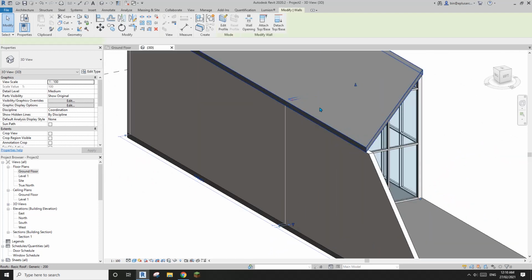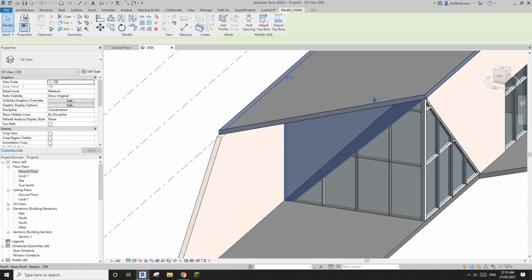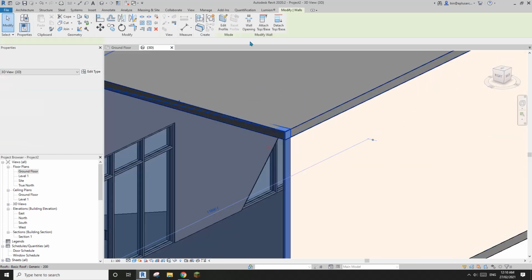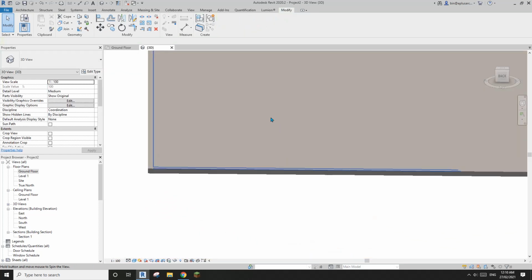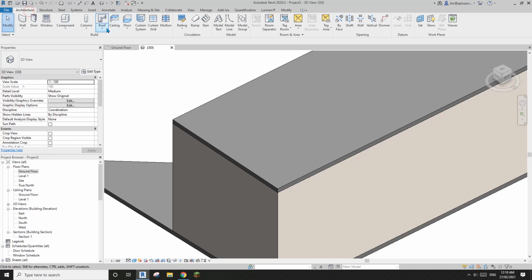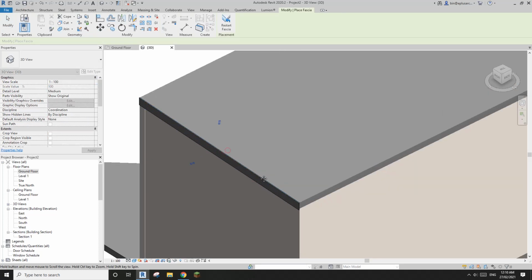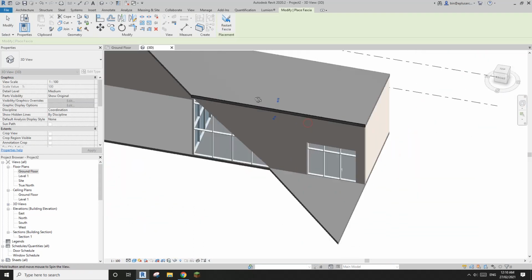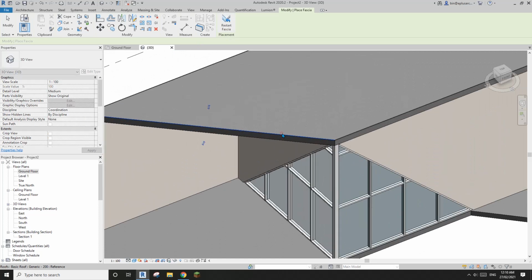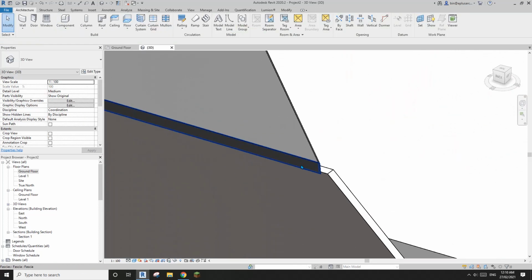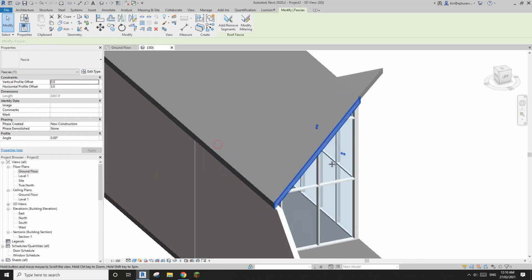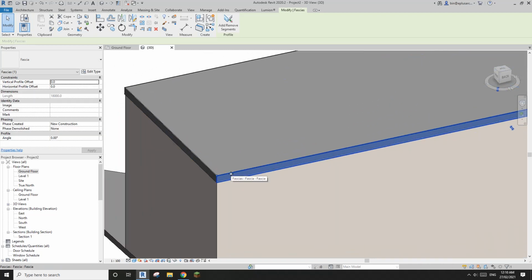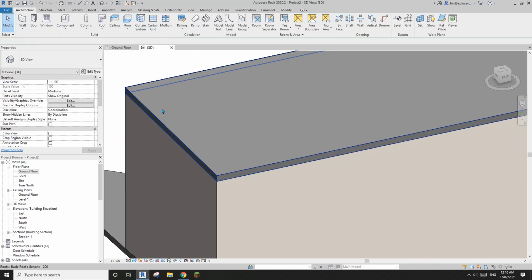And so looks like this wall needs to attach top as well. Okay, and then also here attach top. Nice. And then you can add some fascia board, CS. So I like to create them as separate. So one here. So see, every single one's different. Let me show you why I'm doing this.